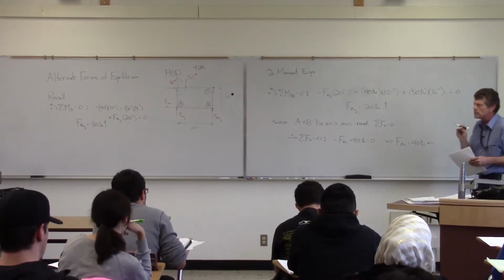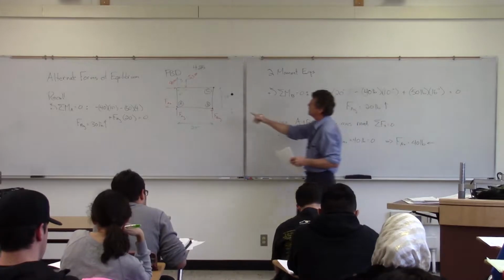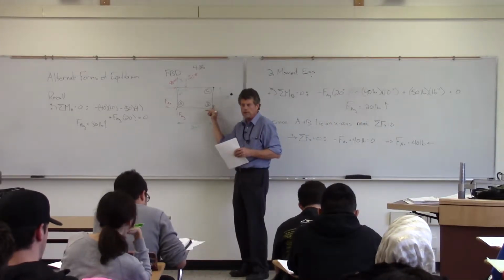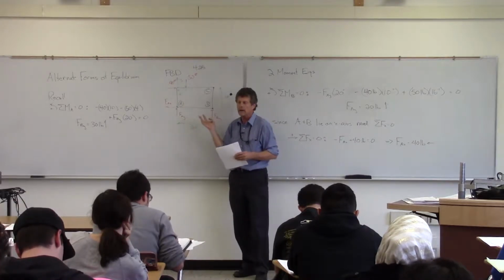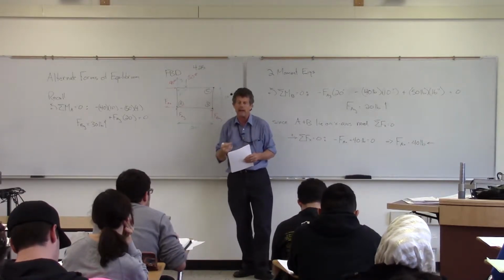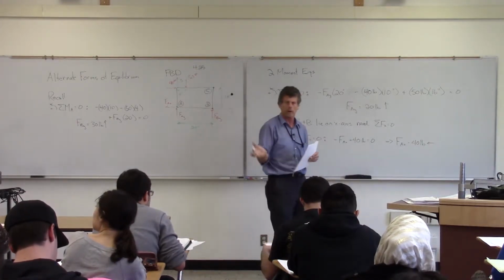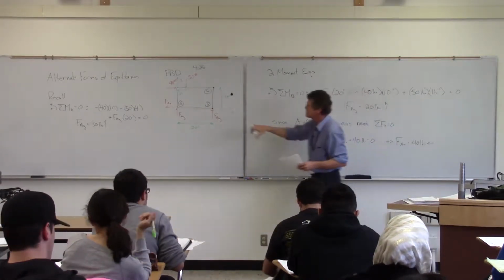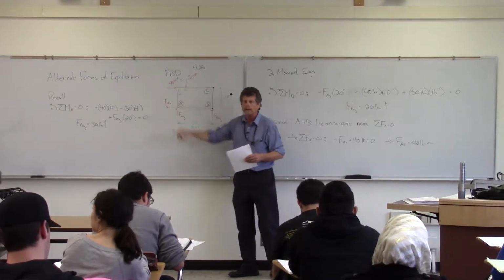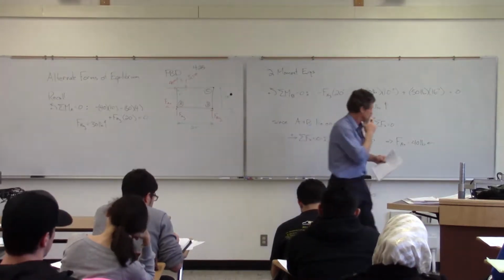The nice thing about moment equations is we can pick points where we eliminate forces. When you think about it, in terms of sum of forces y or sum of forces x, they're all there. They're all going to be summed in there. So if we have 2 or 3 unknowns, they're going to roll right up into that equation there. The nice thing about moment equations is I can pick points where I eliminate unknowns.